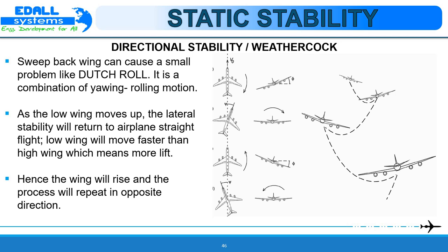One cycle of a typical Dutch rolling motion is shown in the figure here. The physical situation applying in a Dutch roll disturbance can be appreciated by imagining that an aircraft is restrained in yaw by a torsional spring acting about the yaw axis Z. The spring stiffness is aerodynamic and determined largely by the fin. Thus, in straight, level trimmed equilibrium flight, a disturbance in yaw causes the aerodynamic spring to produce a restoring yawing moment, which results in the classical oscillatory motion called the Dutch roll.